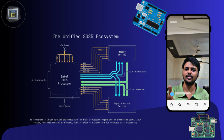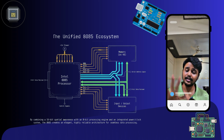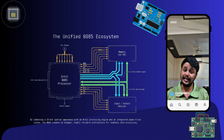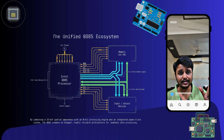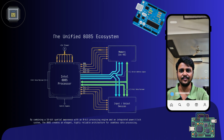The 8080 required multiple voltage levels, whereas the 8085 operates on a single plus 5 volt supply. Another important improvement was the inclusion of an internal clock generator, which eliminated the need for additional external clock circuitry. The 8085 also introduced improved interrupt handling mechanisms, making it more efficient for real-time applications.